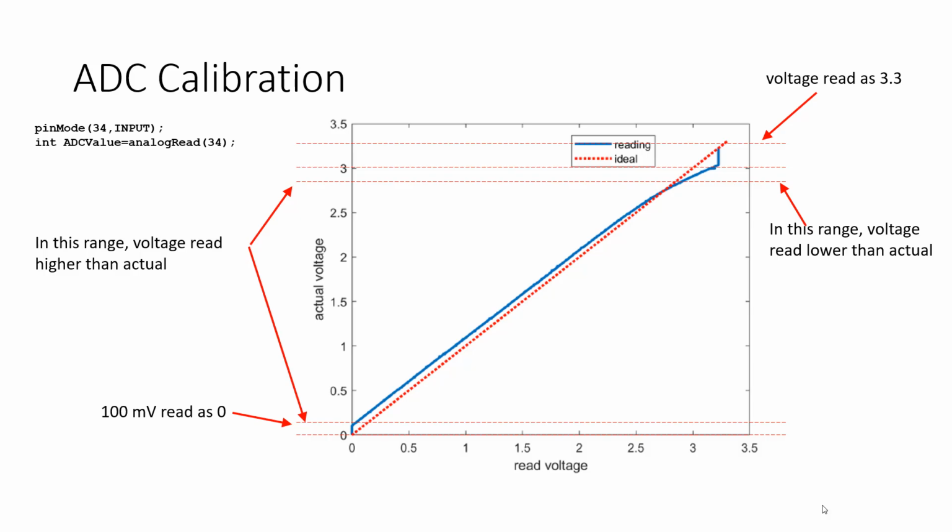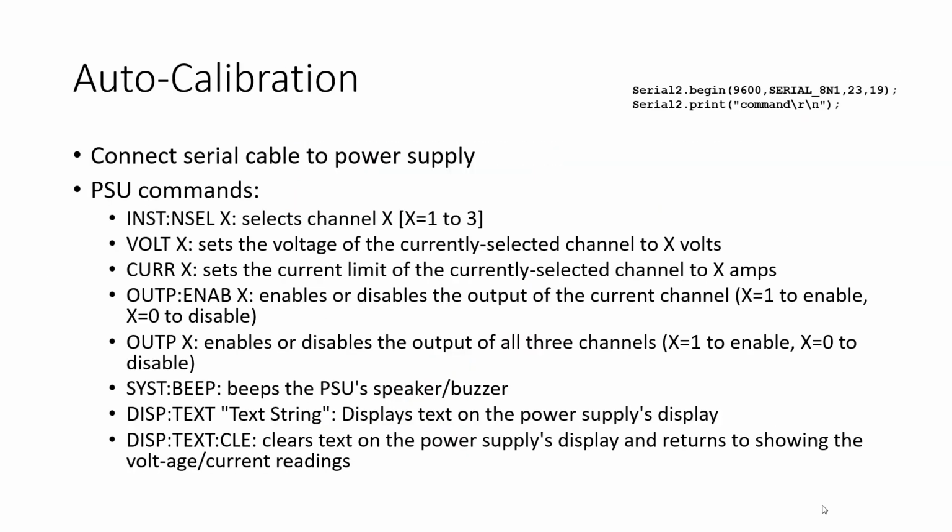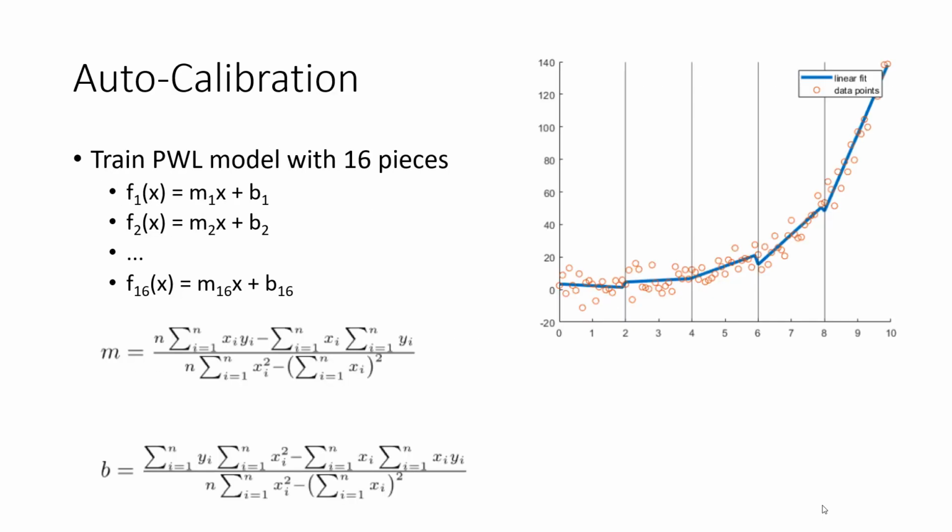That will verify that your calibration is working. So in other words, your program has two phases. It goes through an auto calibration phase, and when it's done, it just sits there and monitors the ADC and prints out what it understands to be on the ADC, including its calibration model. Make sense? Okay, let me talk about the calibration first.